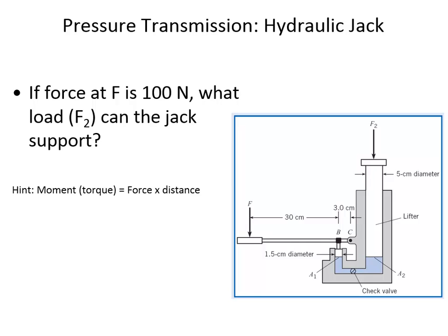So that's why I can split a 12-inch, I can split a 24-inch log just by pushing back and forth on the hydraulic jack, and I'm not even having to press that hard. It's because, number one, my force is being amplified by the long moment arm of the handle. That's a big part of how you get that big force.